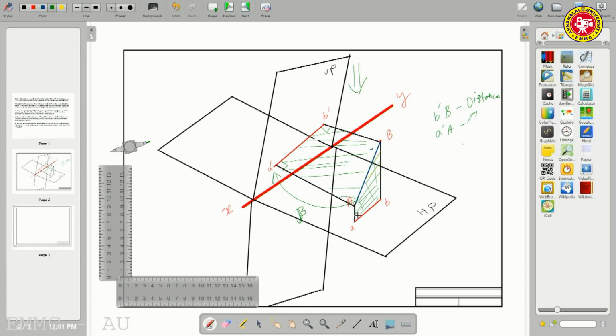So, where you look at this trapezium in front of, from the line AB, in a similar case, from the line AB draw a perpendicular line. Then, what about the distance? A capital A, B capital B, these two, you have to obtain the perpendicular distance and mark it as perpendicular, then we determine the true length. So, what about the inclination with respect to the plane? The true inclinations are theta and beta. Theta is the true inclination with respect to the horizontal plane, and beta is the true inclination with respect to the vertical plane.